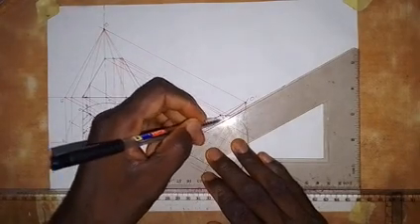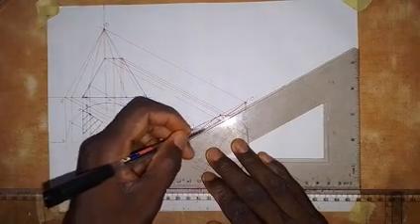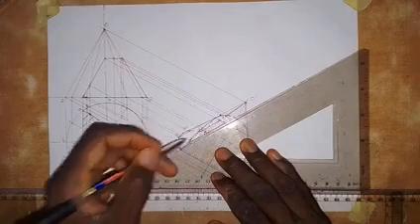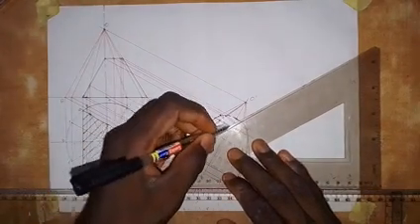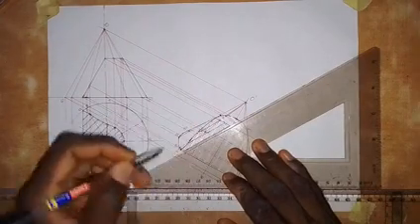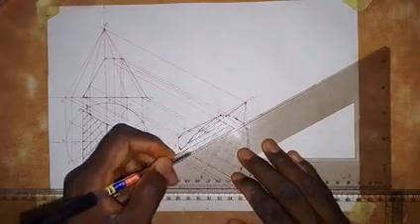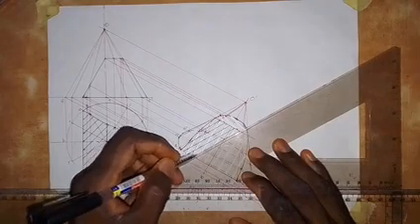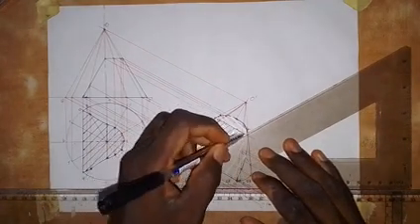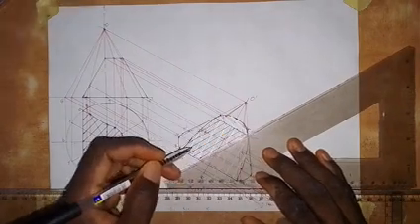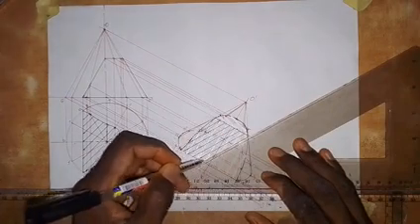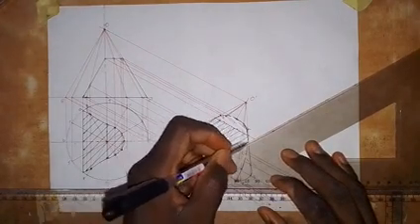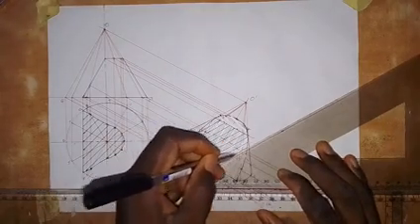So I'm going to produce the arching lines for this large surface. We produce arching lines like this. Don't forget that the arching lines are produced with continuous lines and they are equally spaced. As I said, you don't have to measure the space between them. All you need to do is use your eyes to gauge it yourself. These arching lines that we are producing are correct. It's the angle that we had taken. The one I used 60 degrees for was not okay, so that's why I cleaned it and I'm now producing it properly.